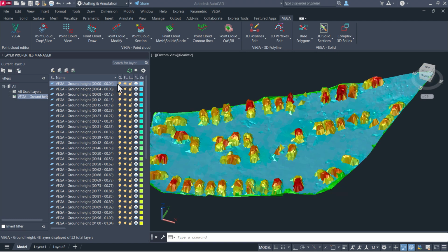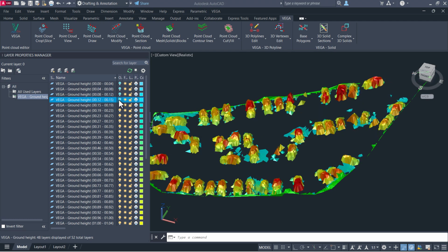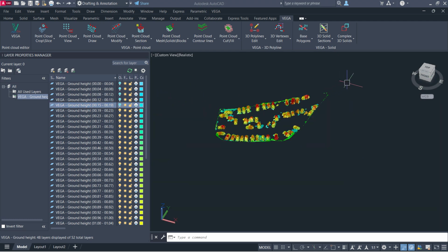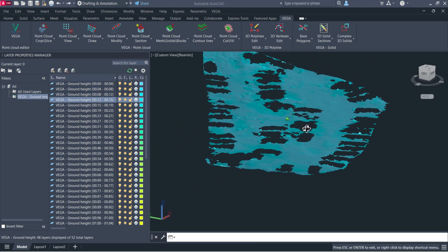I now close the layers that contain the 3D faces that define the ground cover. In addition to the layer name, including the slope, this method makes it possible to see these 3D faces very well. It's a very accurate method. I'm selecting objects and deleting them. I erase the objects that are foreign. In this case, it's mostly cars. Let's see what we've got.